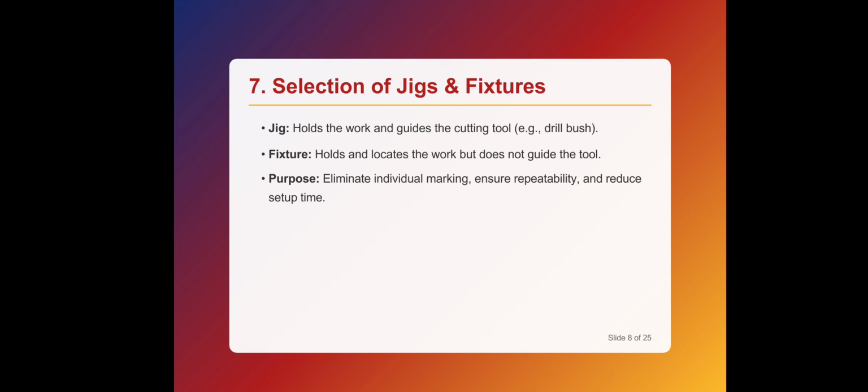Also, the selection of machines is an example. Once the appropriate type of manufacturing process has been determined, the next step in process planning is to select appropriate machines, equipment, and tools to accomplish the required operations. So there are many factors which influence the selection of machines, such as production rate and unit cost of production, durability and dependability, minimum setup and put away times, functional versatility, that is ability to perform more functions, etc.